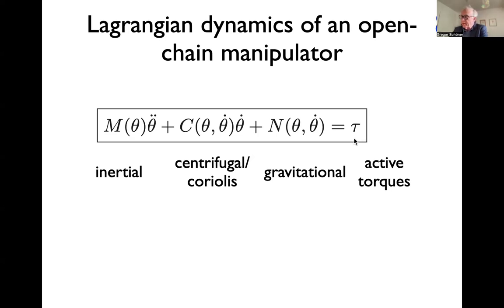There's a vector that for every joint that is showing up here, you have a torque vector, and that's what your electrical motor does. So that's just the mechanics per se, and now the control consists of inserting the right torques to achieve the right thing. Yeah? This means inserting the torques as functions of time that you want to get the right movement. You have to have a model to do that.